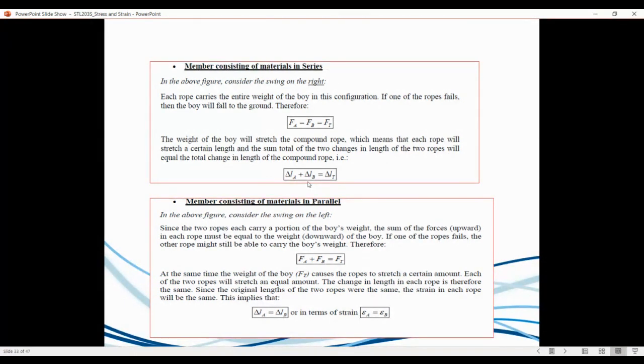Think about these arrangements. This is analogous to having lamps or lights, and normally we connect them in parallel because if one circuit goes, we still have the other circuits. However, if you have it in series, if something happens in that specific circuit, then there's no current going through it, and all the lights won't work.